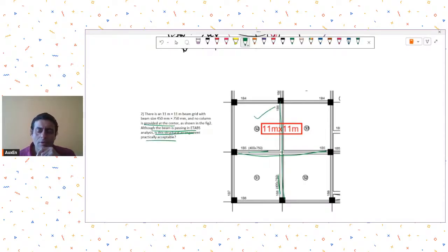Yeah, why not? This is acceptable as long as all your design checks are passing and your deflection limits are well within control. Remember that if you are doing just the normal deflection calculation for dead plus live, it is the short term elastic deflection, but that deflection value will be much higher if you go for the long term cracked section deflection.